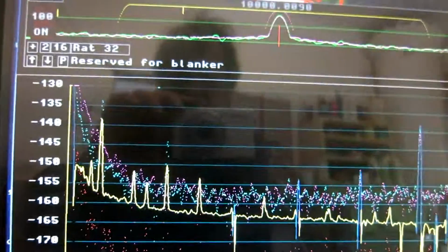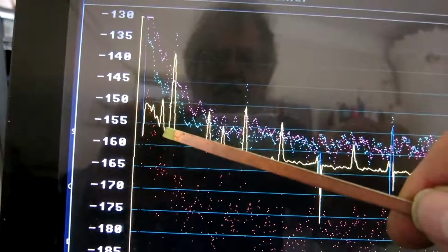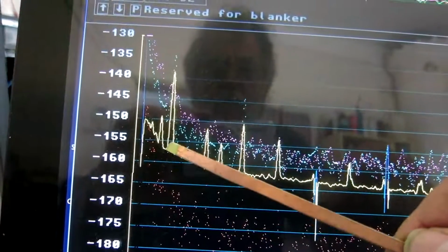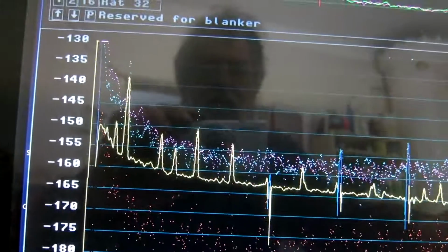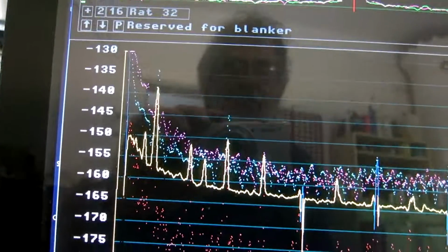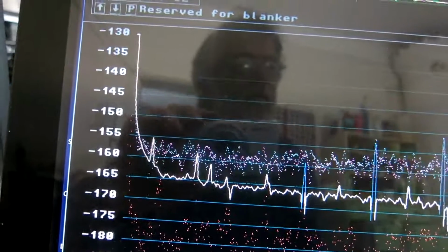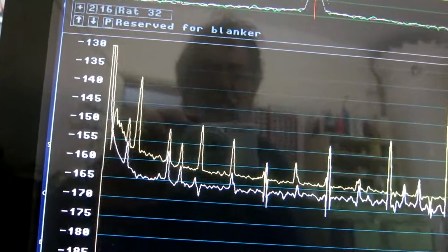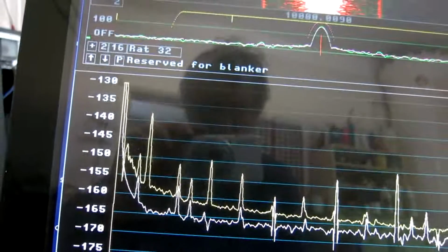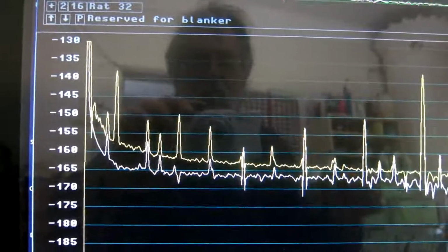Already after 1 hour and 15,000 averages, the result is accurate enough. As I can see from the position of the imaginary part, it is about 10 dB below the real part at 50 Hertz, and it's better at higher offset frequencies. And this is the phase noise. And I look at the amplitude noise, and here it is even better. So I can take these curves and use them to read the sideband noise at different frequencies for this oscillator.